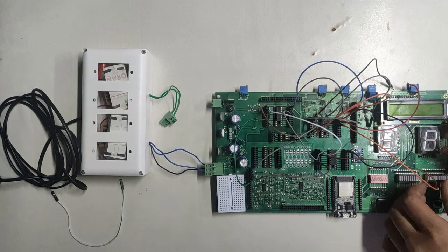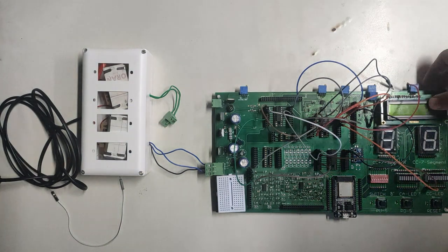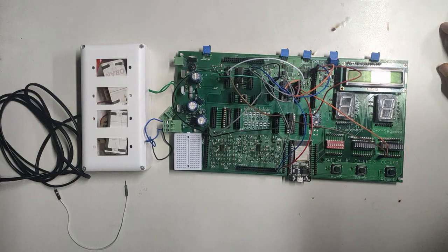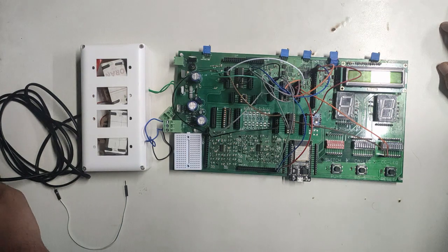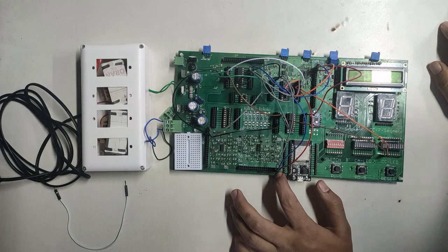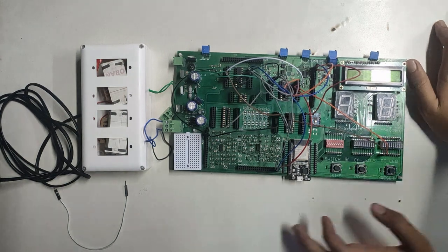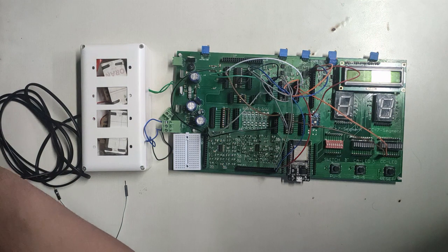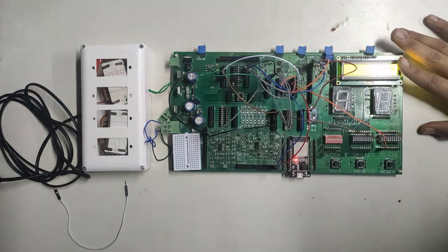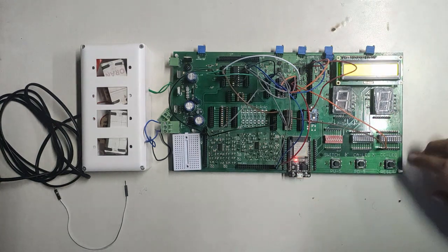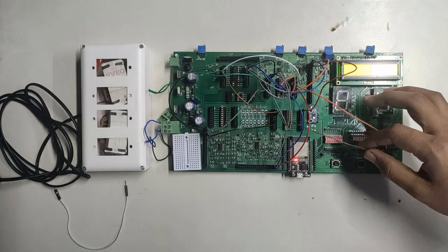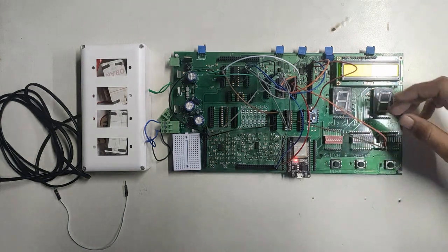Now let us verify the truth table of full adder. So after making the proper connections, now let us verify the truth table. In the first case, when all the 3 inputs are connected to the ground, which is logic 0, the expected output is 0, so let us check. So yeah, none of the LEDs is glowing, so we can say that when all the 3 inputs are 0, the output is 0, which is the sum is also 0 and carry is also 0. The brown wire here indicates the carry and the orange wire here indicates the sum.